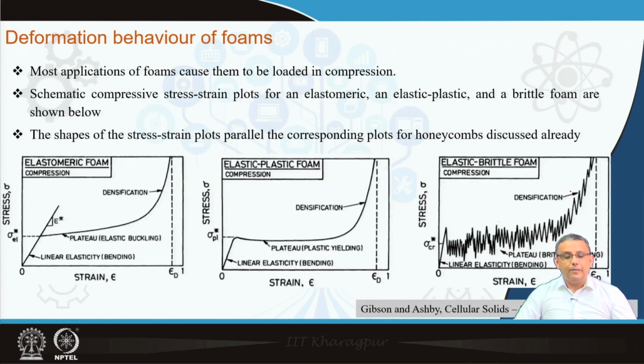Okay. As we learned about the honeycombs, the compressive stress-strain behavior of honeycombs had 3 regions: initially the linear elastic region, then the long plateau region, and then the densification region. The same 3 deformation regions are also present in the compressive stress-strain behavior of the foams. The difference between foams and honeycombs should be clear by now, as we learned already.